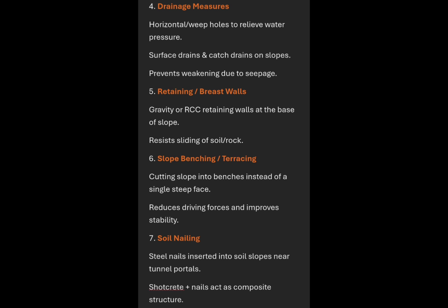And number six is slope benching, or we can say terracing. Cutting slopes into benches instead of a single steep slope. We can't construct a steep slope. We construct it in small slopes, then provide benches and proceed forwards. It reduces driving forces and improves stability.